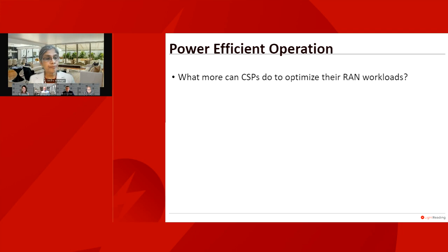And then advanced silicon telemetry and power management. So you have power management features built into the silicon, what we call P states to turn down the frequencies, what we call C states to go to micro sleep, so that you can utilize all these and be able to get very good dynamic power efficiency as well.